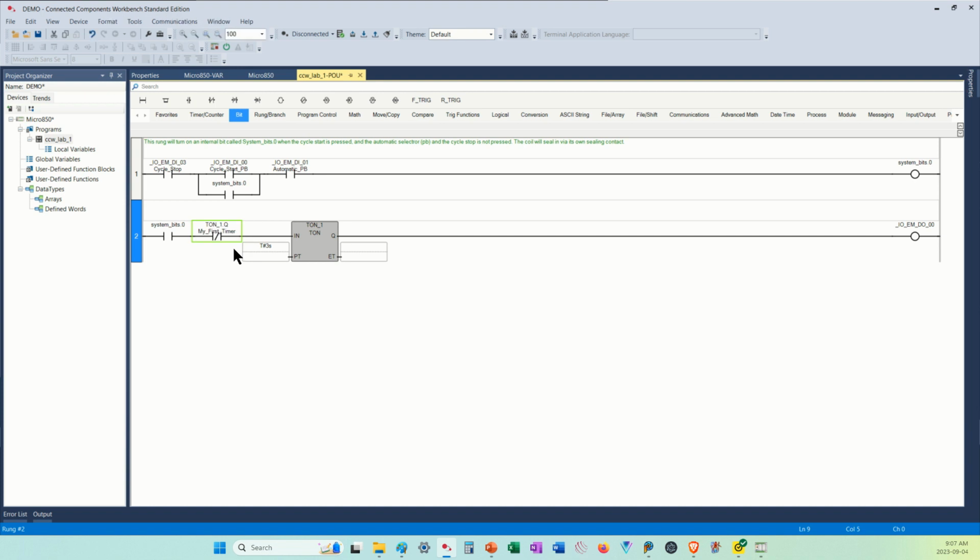So what I've just basically done is that when my timer is not finished, time. But if I'm finished, stop. And when it stops, it's not timing, which then means start timing again. And then when it's finished, stop. And then start timing again. So this is going to cycle itself. We used to call these a free-running timer, and there were lots of applications for it when you wanted a heartbeat, when you wanted a flash, or something along those lines.